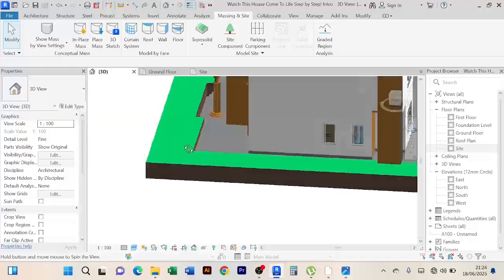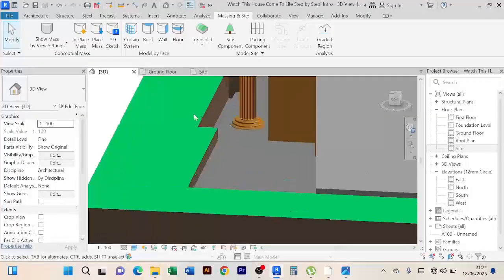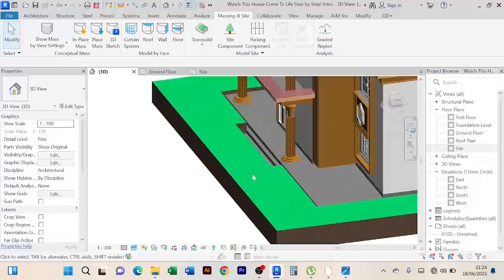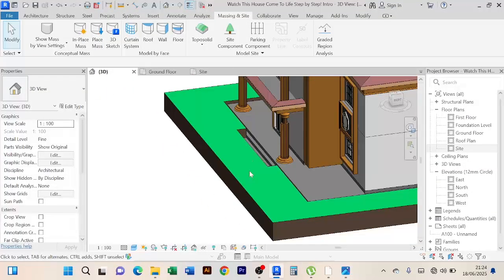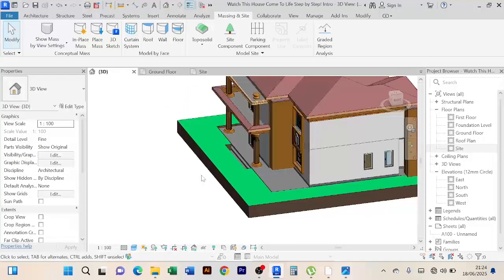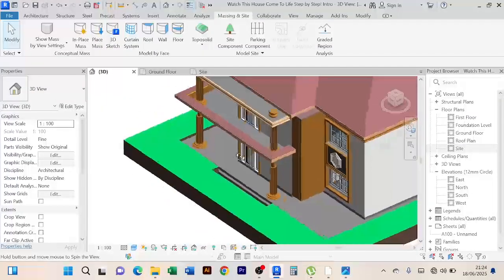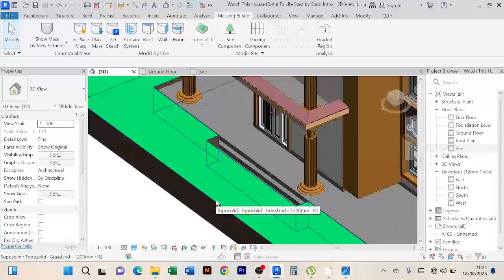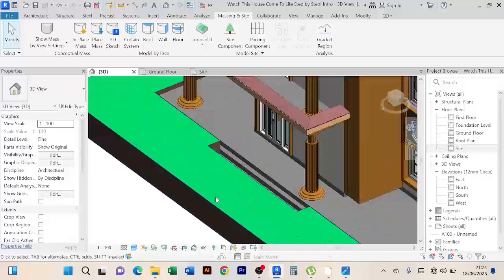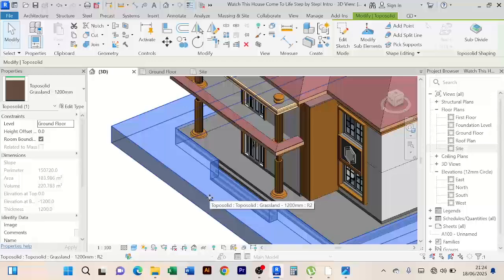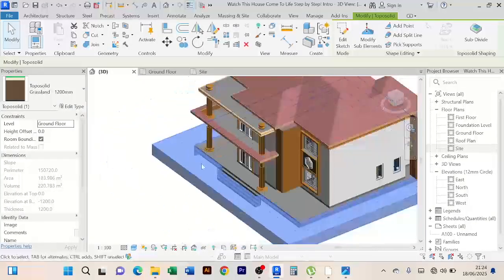Now the house is okay, but we still have a problem this side, because now the house is a little bit down and our toposolid is a little bit high. That means we need to cut off some parts, what we call a subdivide. You can subdivide this and also create something that makes sense for how people are going to access this house. See that? Now we are going to reduce the thickness of this toposolid so that it's not really too big.